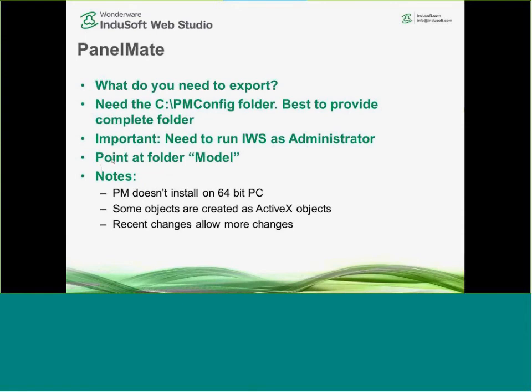In that PanelMate config folder, you're going to find another subfolder called Model. And when you do your import, if you just point at that Model folder, that will give you all the different projects that you've brought in from that PanelMate configuration.